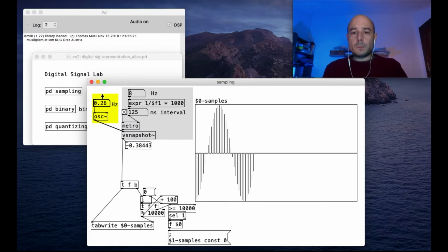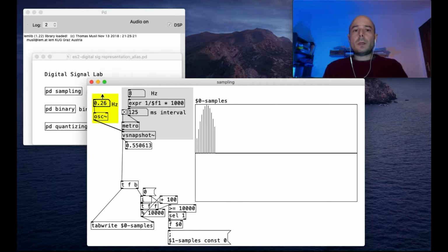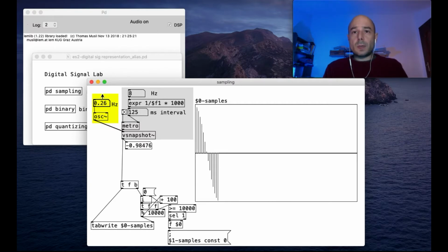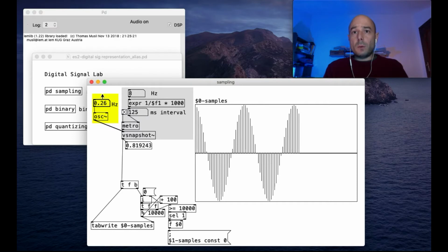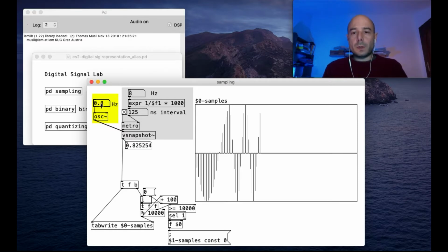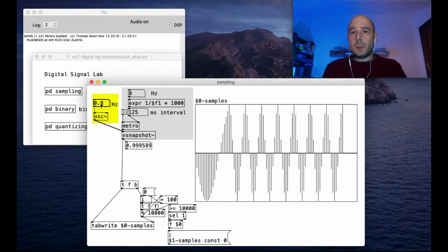frequency without any problem. We can also compute the number of samples needed for a single period of a periodic signal by the fraction between the sampling frequency and the signal frequency. If the result is an integer, we have a finite number of samples for one single period, and if the result is a rational number that is not an integer, we have a finite number of samples for a multiple of one single period. For example, let's choose 0.8 Hz for the signal frequency, and we obtain a sequence of samples made by 10 samples per period.